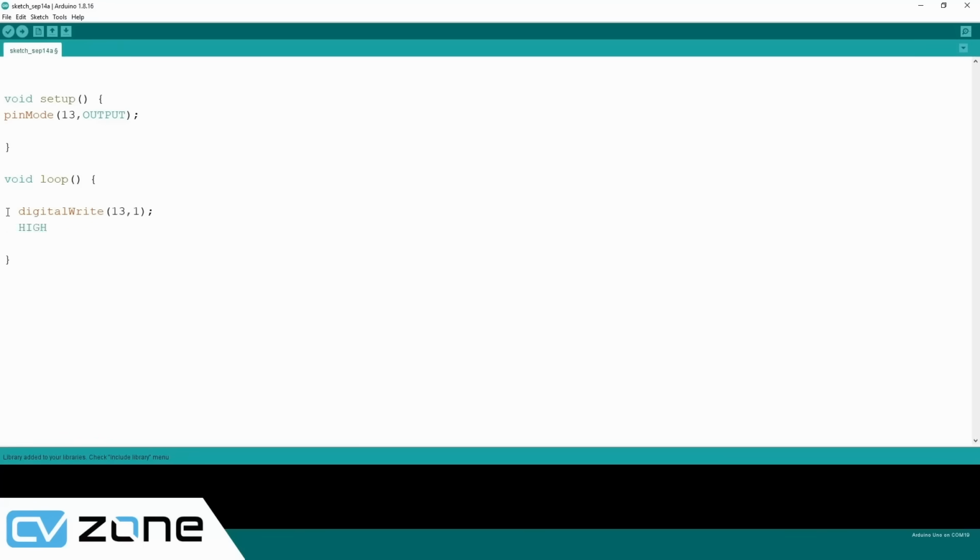But if you write HIGH, you have to write capital letters. You cannot use H capital and IGH as small, so all of them need to be capital. Then we can simply put a delay of, let's say, 1000 milliseconds. And if you want, for example, 5 seconds, you would write here 5000. If you wanted 10 seconds, you would write 10,000.